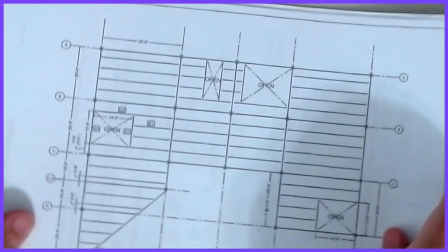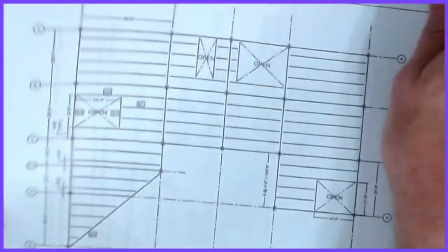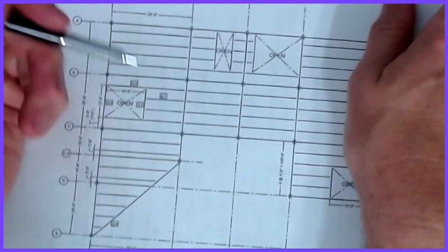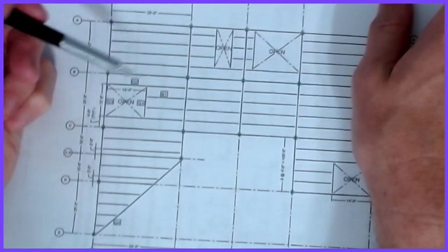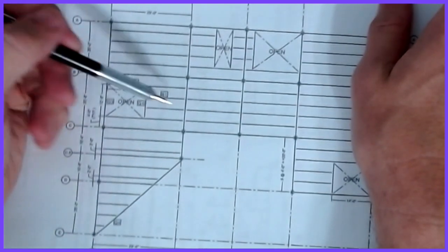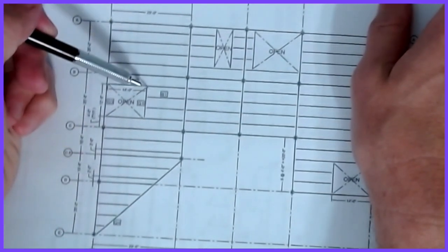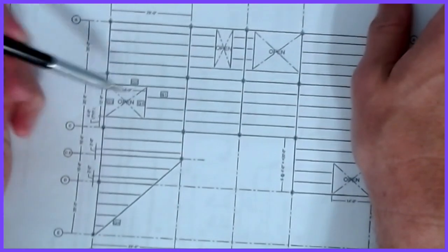Okay, all right. So that leads us into our class exercise, and of course I ramped this one up a little bit, and I'll talk a little bit about it and let you work on it, and we'll talk about it next time. What do you do about openings on here? Openings are a little bit different, because now we're starting to cut some beams short. Like B1 here only goes from here to here, but now I've got a girder around this opening, because you have to frame an opening.